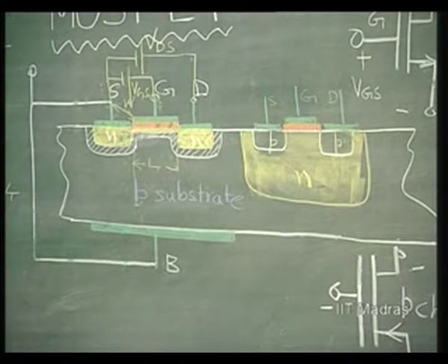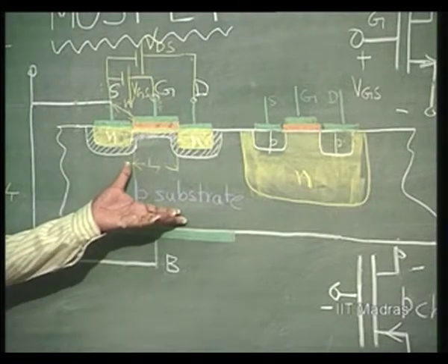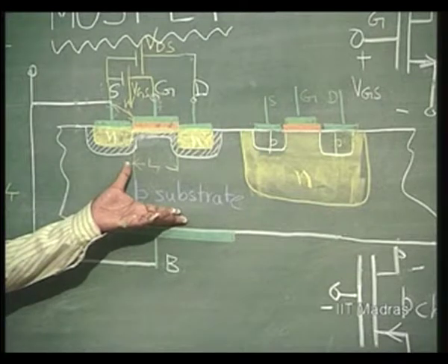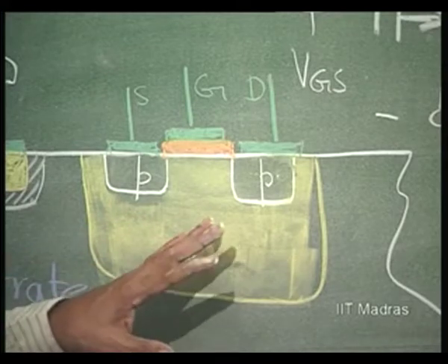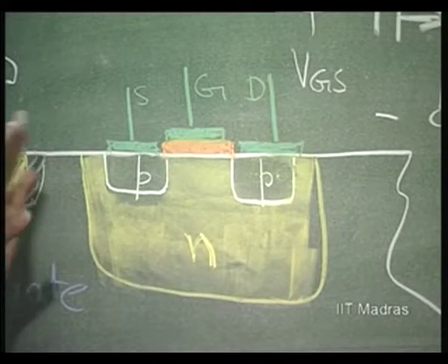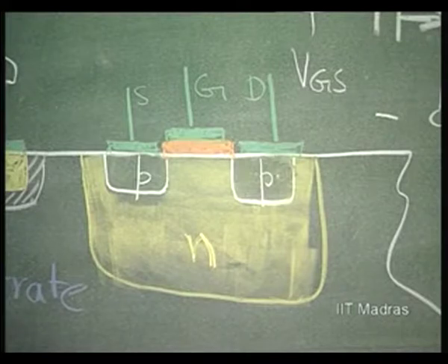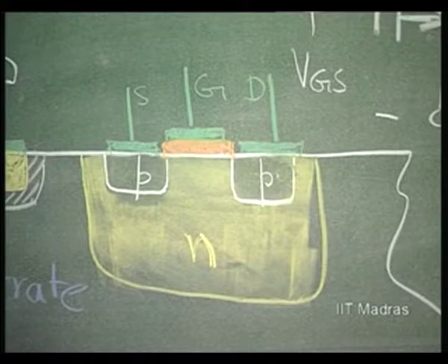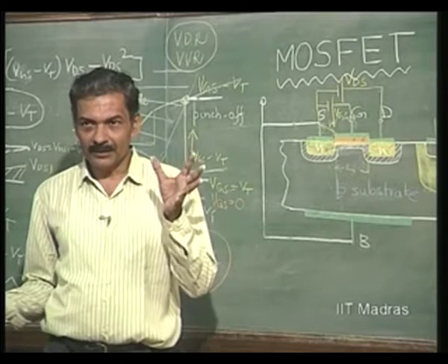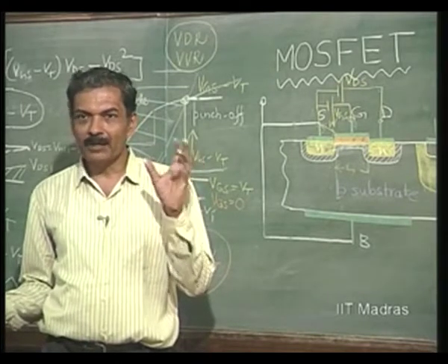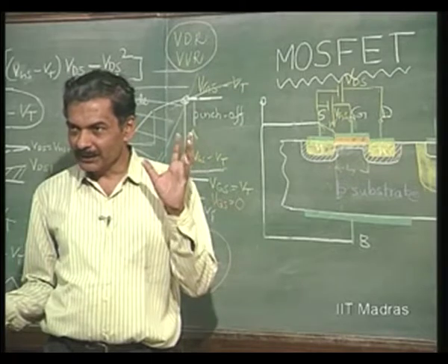This is called CMOS, complementary MOS. This technology of fabrication is called CMOS technology. You can have a technology where we do not have the P channel at all, only N channel MOSFETs throughout. So, you can have N channel VLSIs, P channel VLSIs or CMOS VLSIs. These are the three different technologies available for fabrication of very large scale integrated circuits.